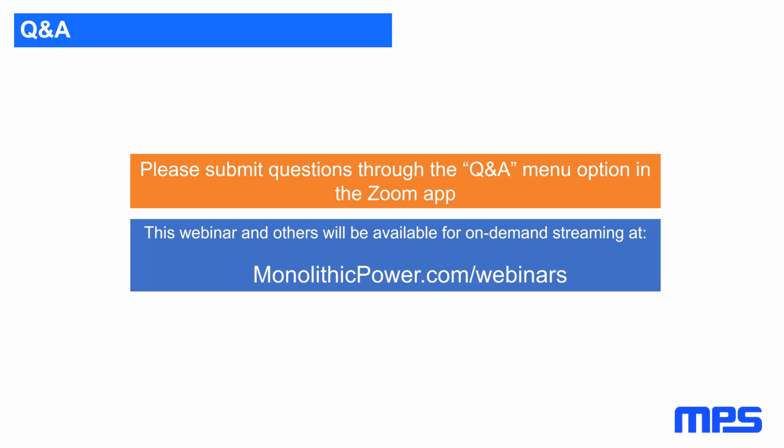All right, another one here. Does this information apply to unipolar stepper motors? So yes and no. Unipolar motors are driven a bit differently. Instead of an H-bridge, normally there are 4 low side FETs. And there's a center tap winding that goes to the supply voltage. So the way they change the current direction is they drive one or the other of these 2 low side FETs against the center tap to move the current direction back and forth.